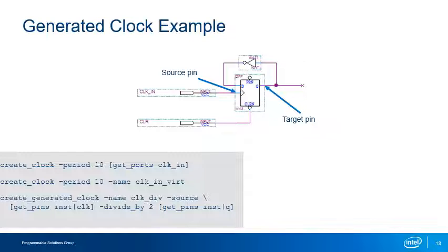When performing an I/O timing analysis with these clock constraints, clock invert will be the launch clock and clock in will be the latch clock. Adding the extra virtual clock in this manner will also let the timing analyzer automatically add I/O timing uncertainties using a command we'll look at in a moment. This can help in performing a timing analysis that more closely reflects real-world timing.